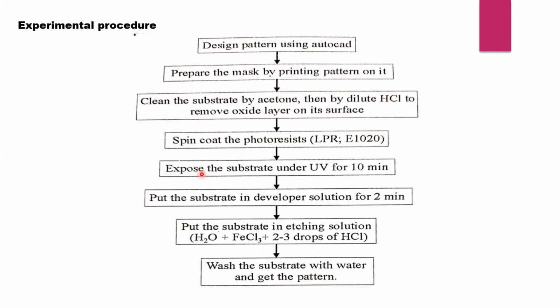In the next step, we have to expose the substrate. So don't forget, students, our substrate is not free of photoresist. Photoresist is there. That should be exposed under ultraviolet radiation for 10 minutes.